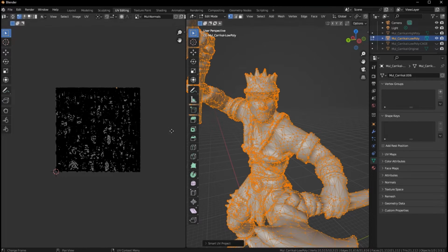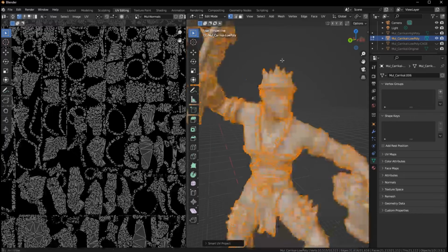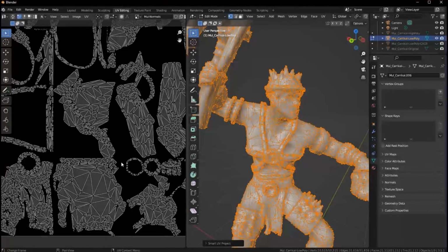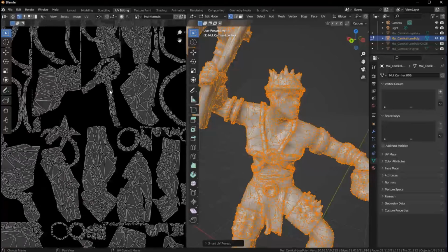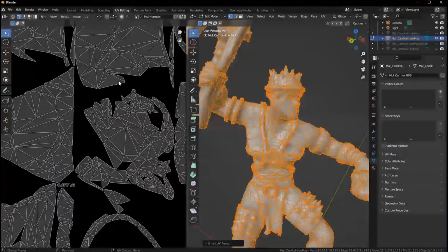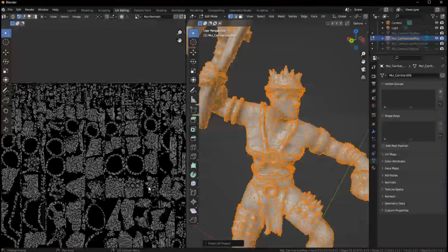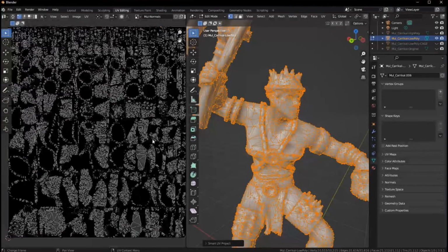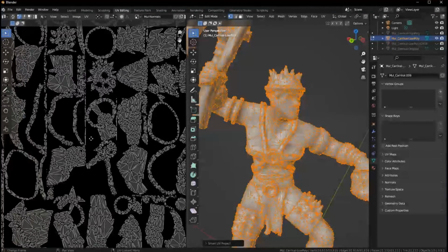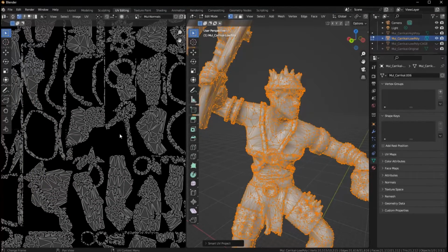What we're looking at here now is all of these facets flattened out, like if I were to take this and cut it into pieces of paper and try to lay it out flat. That's what Blender tries to do. It creates a flat version of all these pieces. Now, if you're familiar with 3D modeling for digital environments, you know that this is not the best UV unwrap.